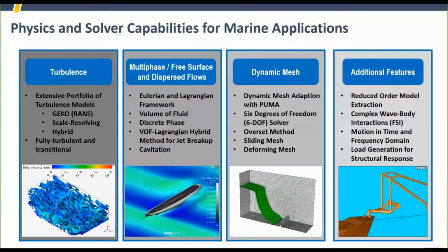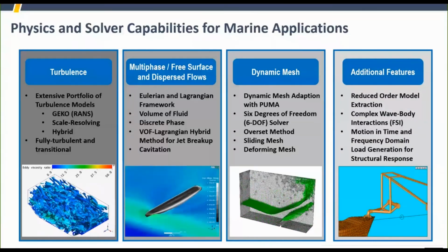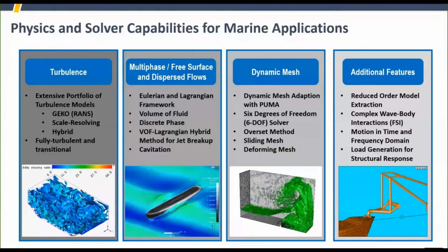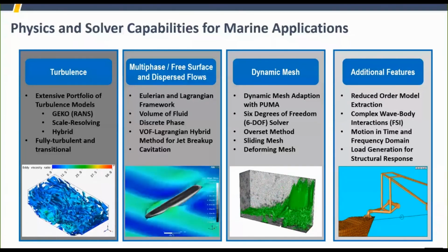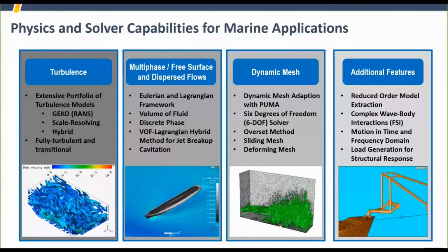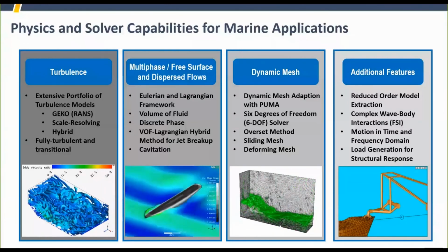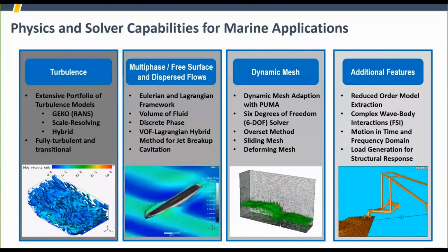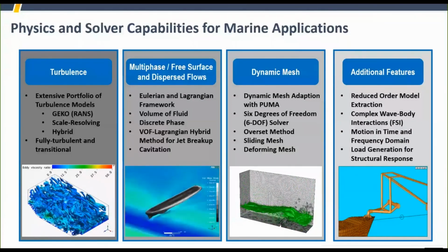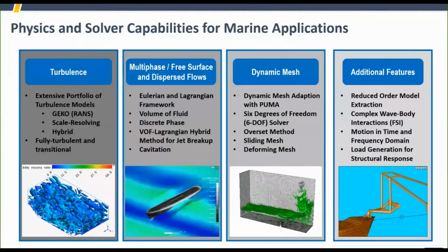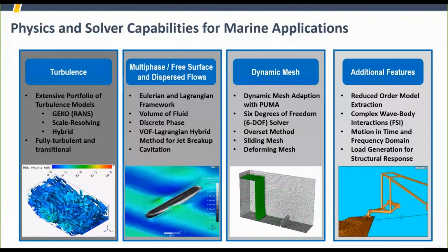Often we need to do fluid structure interaction type of simulation that allows us to resolve the complex wave-body interactions. The motion can be studied in both time and frequency domain, and load generation for structural response is an important feature that is provided by the CFD tools.